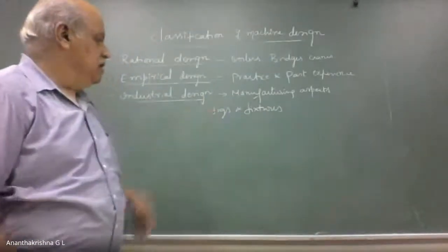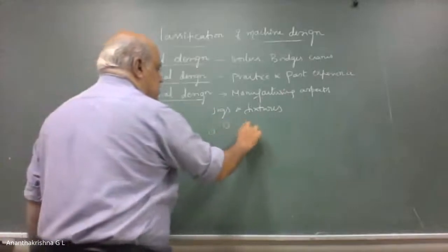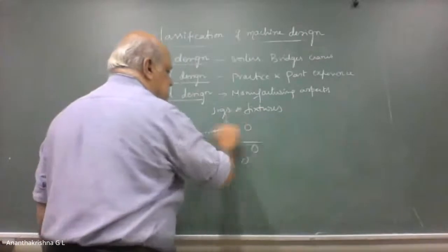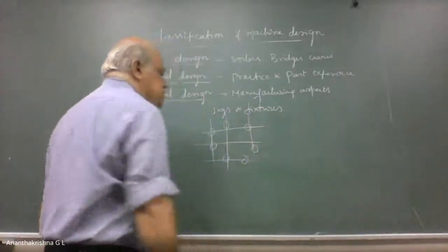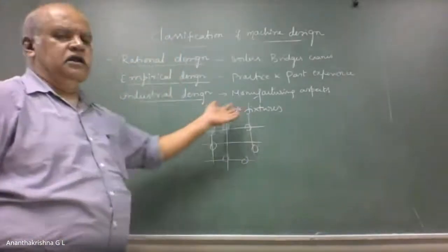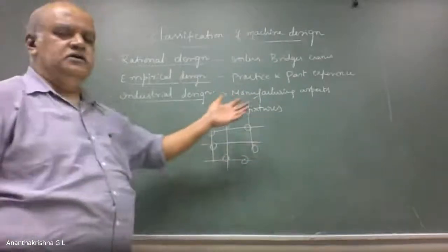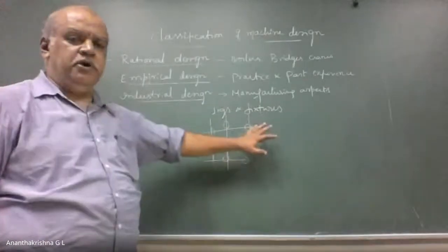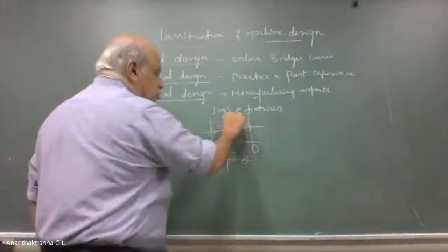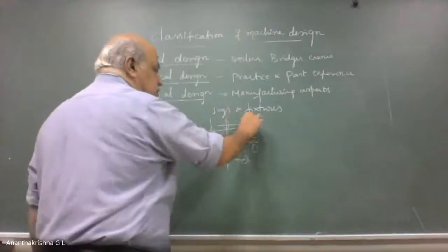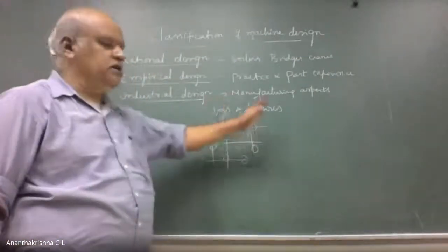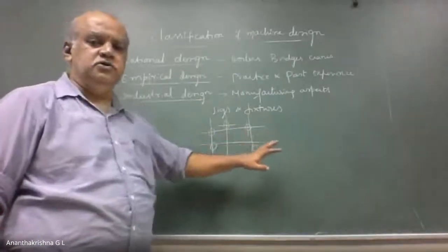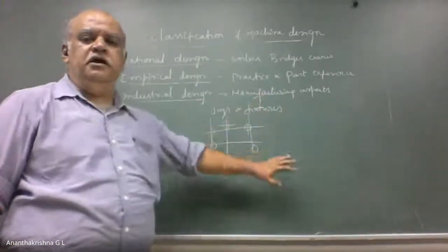Say, for example, you have to drill several holes with different pitch and different diameters, and they need not be on one pitch circle. When you have to mass produce such components, you cannot locate every hole and then start drilling. It takes so long, and the accuracy will also be a problem.